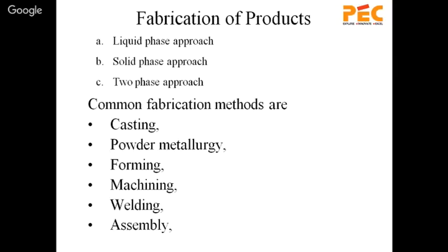If you want to make a hybrid, you can put both together, and agitate for 2 hours. The agitation temperature should be at least 1250 degrees centigrade, which is above the recrystallization temperature of this particular reinforcement material, and you allow another 2 hours at that temperature. Then you take out this agitated material, put it into your molten aluminum as the matrix, stir it, and then put it into the prepared cavity or metal mold cavity.